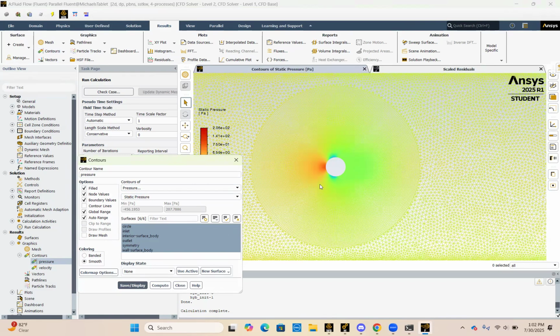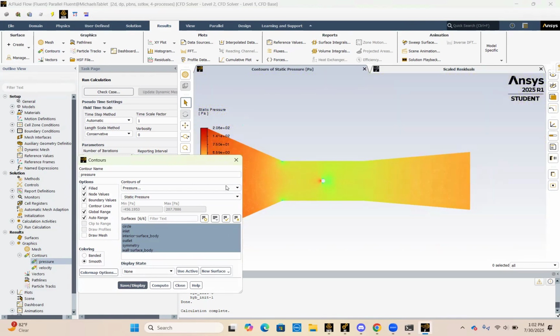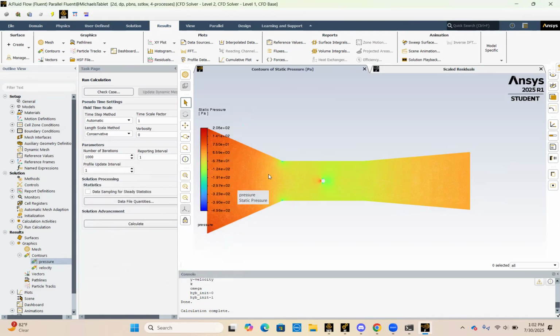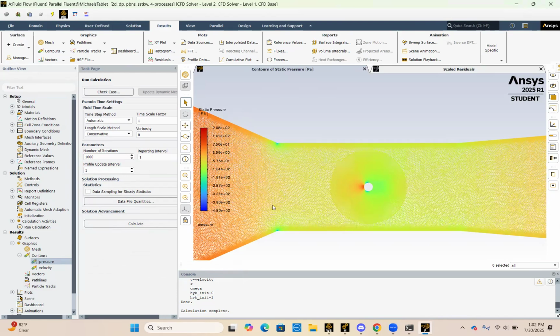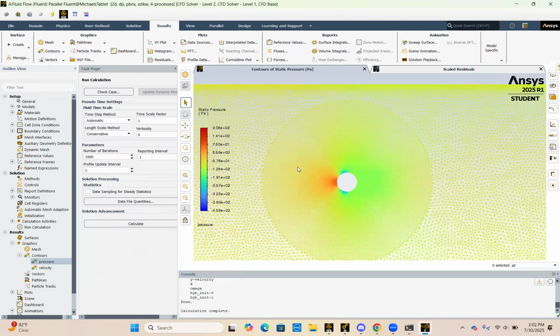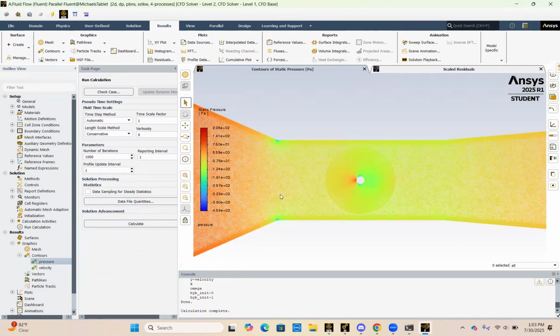All right, so now if we zoom out, we of course see our higher pressure coming in. Where it's very fast along these edges, we see our low pressure. As we know, velocity corresponds to an increase or a decrease in pressure, sorry. If we zoom in even further, we can see our stagnation point where there's the high pressure zone forming in front. See the low pressure zone where we have our increased velocity, and then we can see some wake where the pressure is also somewhat lower than, say, right in the front here.